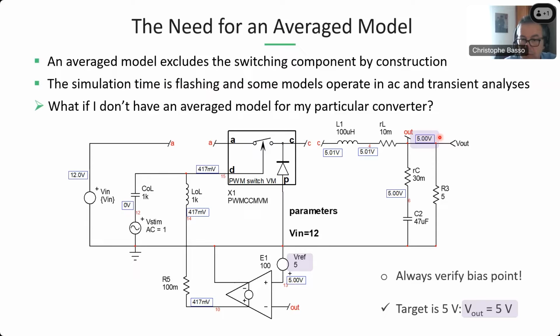So obtaining this transfer function via simulation or on the bench with the Bode 100 frequency response analyzer truly represents the cornerstone of any stabilization exercise. Without it, you cannot seriously think about a compensation strategy. So it's truly what you need to start with, the control to output transfer function.